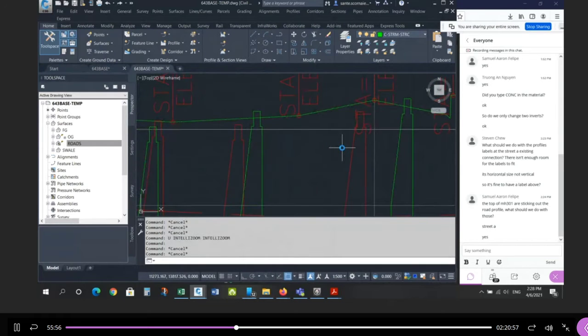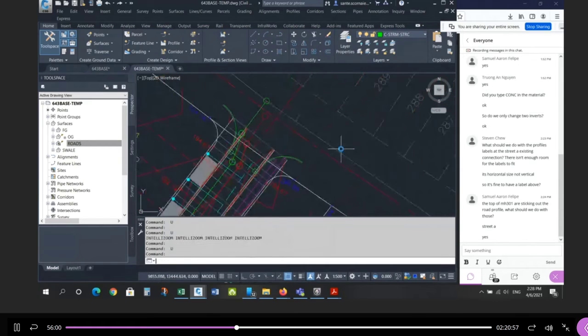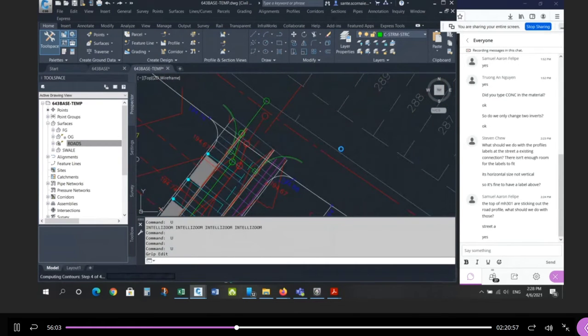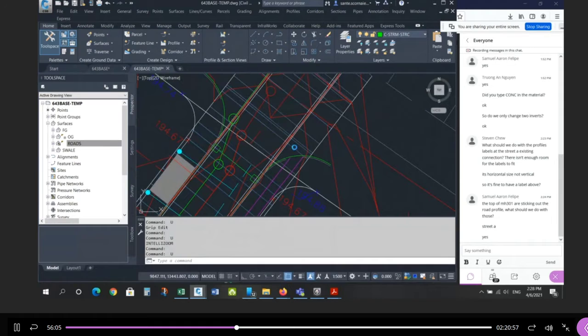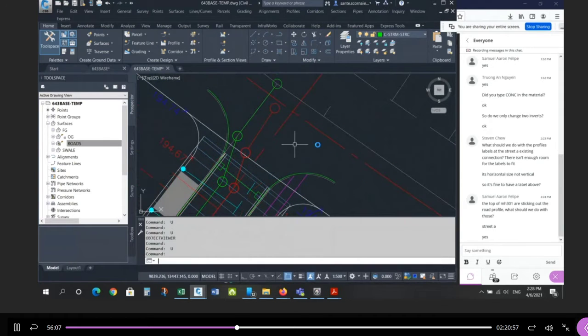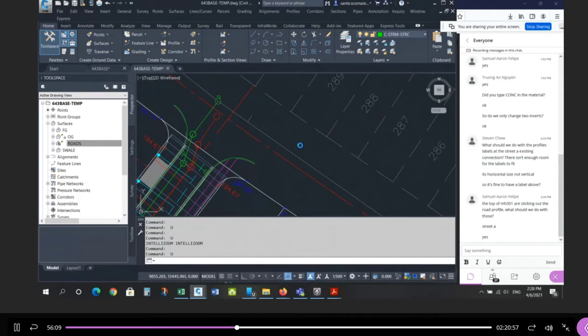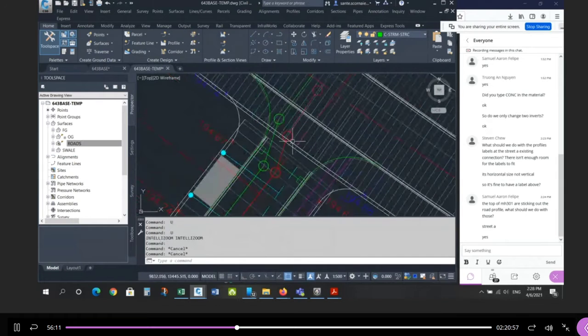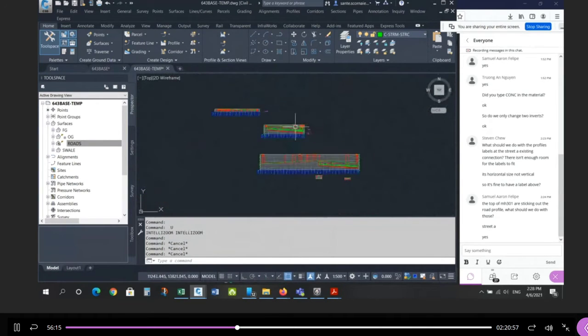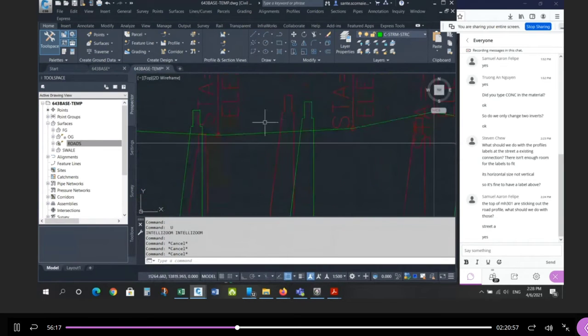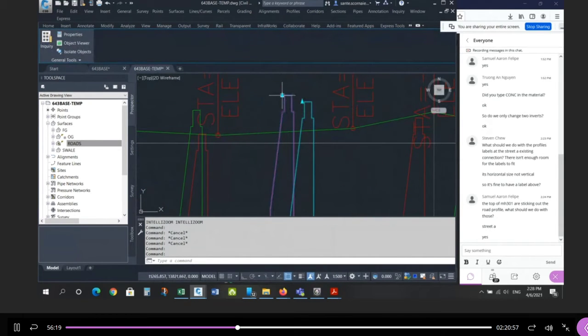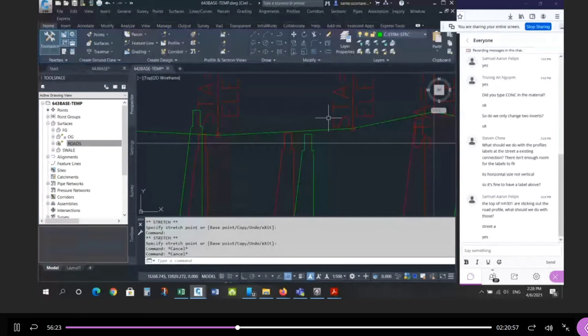If you don't want to make the surface perfect so that the manholes come out correct, just do this. Watch, I'm going to undo all my revisions. I'm going to bring ledger way back. So do you understand why they're too high, right? They're actually in the boulevard, not in the pavement. So this is the simplest thing to do. Just take these and grip edit them down. That's all you need to do. You know they're down below.